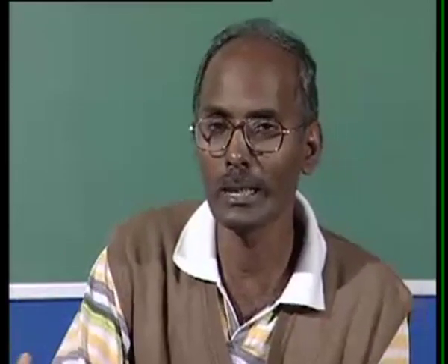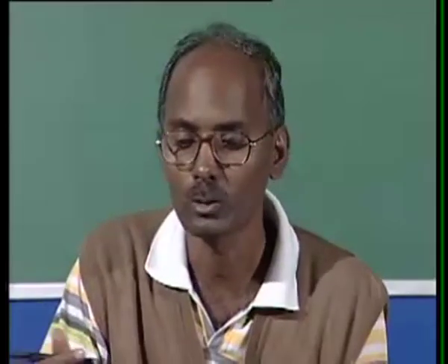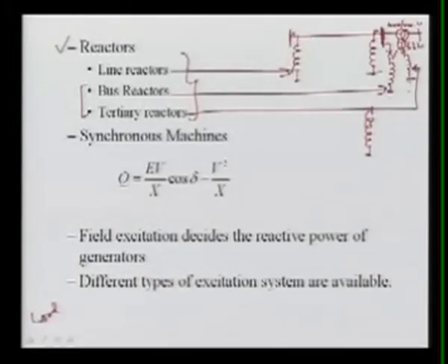Nowadays again we are feeling there is a huge surge in the voltage, meaning voltage variations are very high. So now we are talking about why not put some reactor with a thyristor, a TCR, thyristor controlled reactor, meaning we can control the reactance value. Sometimes we unnecessarily reduce the voltage, so that we can maintain the voltage at a specific per unit value. But putting in these thyristors, the cost will increase, and nowadays in several places in India we are having the TCR rather than a simple inductor, that is, reactor. So that is also possible.